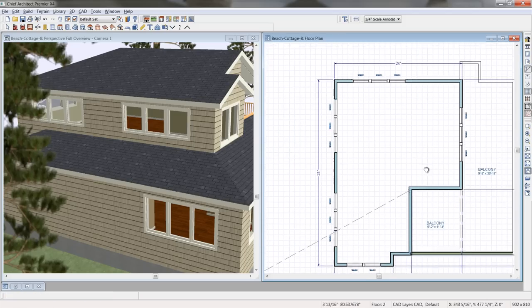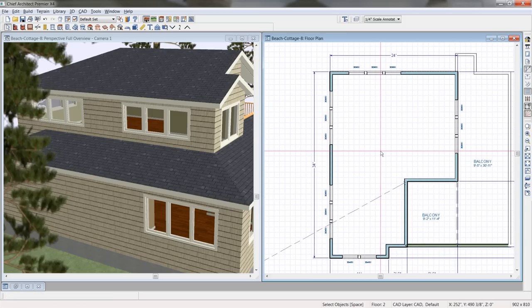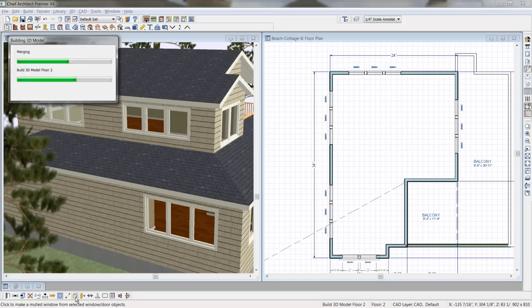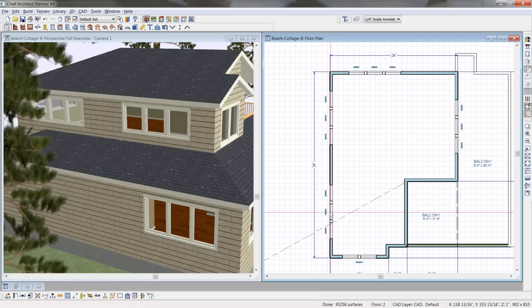Okay, now the final thing that I'm going to do with the windows, when I frame this, I want it to frame the windows as a single unit. So I'm going to block these windows together. It's also called mulling. So I'll highlight in the gable here. And then in the lower menu here, it says Make Mull Unit. What that's going to do for us is when we do the framing, it will frame that as a single opening. So I'm just going to select these windows. I probably could have done this before I did the copy operation, and then I wouldn't have to select each one of them and block them together.